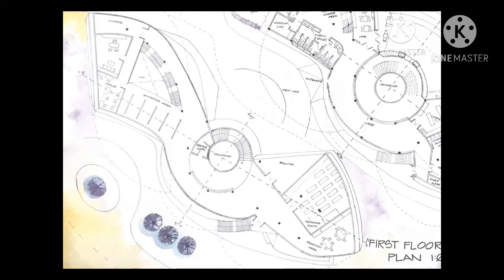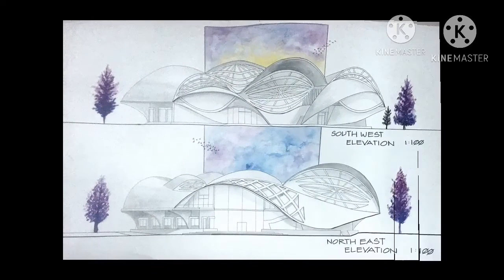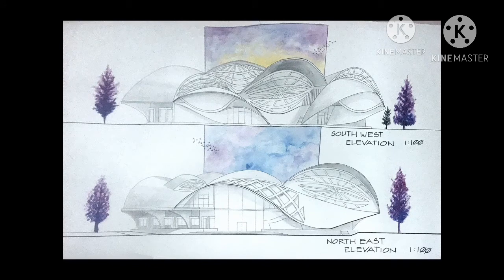On the first floor, there are office, balcony, service room, seminar room, and reading room. At the first floor, you can enjoy the view of the sea because there is a huge glass window. From what you can see from the southwest elevation, there are many bigger openings integrated with operable louvers at the wall and also at the window to collect wind from the southwest during daytime for natural ventilation. So this design can reduce the energy use in the building.